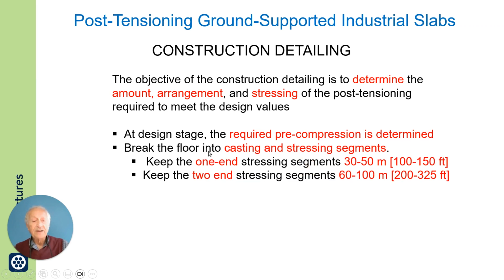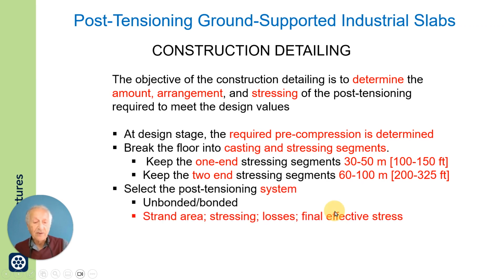Then you break the floor into segments of either stressed at one end or stressed at two ends, and typically the segments will be 30 to 50 meter long, 100 to 150 feet, or if stressed at both ends will be more than that, will be twice.